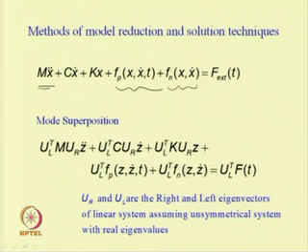So one can write the nonlinear term also. This is the external force acting on the system, this is the nonlinear force we are taking, and this is the localized parametric excitation force, which is defined in terms of displacement, velocity and time. Then this is the force due to stiffness, this is the damping force, and this is the inertia force of the system. These are the forces acting on the system, and one can write the equation of motion by using any method, including the finite element method.